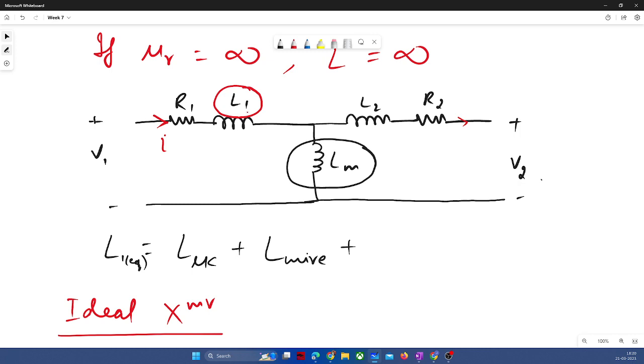I am just talking about primary inductance apart from magnetizing inductance, only leakage and wire inductance. Okay. So, sir, seen from the source, Lm also will be taken into account. Yeah, if you compute the equivalent from this point, then your Lm will come. But I am just talking about this L1 equivalent, not L equivalent.